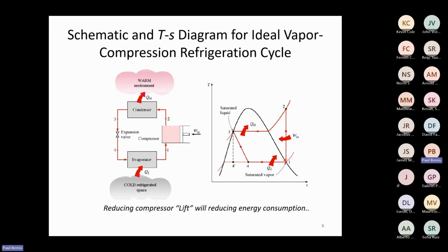It's causing, from point 1 to point 2, I've got to put shaft power into that device in order to lift or pressurize high enough such that T2 is high enough above ambient so I can dump it to the atmosphere. Very critical, because if this atmospheric temperature is high, this lift will go way up. And if the lift goes up, of course, pressure and lift are synonymous. And what happens is you'll trip that chiller.